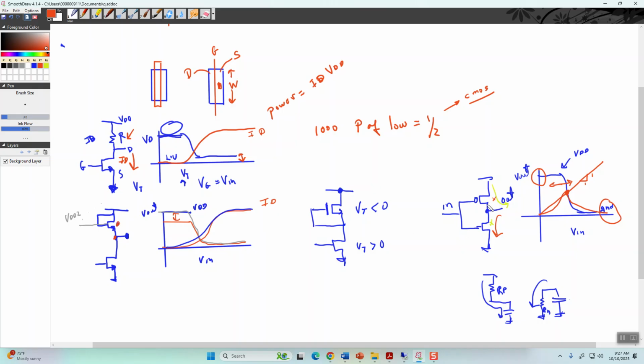Now let's take a quick look at the power in CMOS. And first of all, we have something called activity factor. What is the probability that this gate, or any gate, or all the gates are switching? So it's something between 0 and 1. And if the clock is stopped, it's 0. So the power would be 0 in standby mode. Now then you have, how often are you switching? So that would be your clock frequency. All right. Then you have the load capacitance.